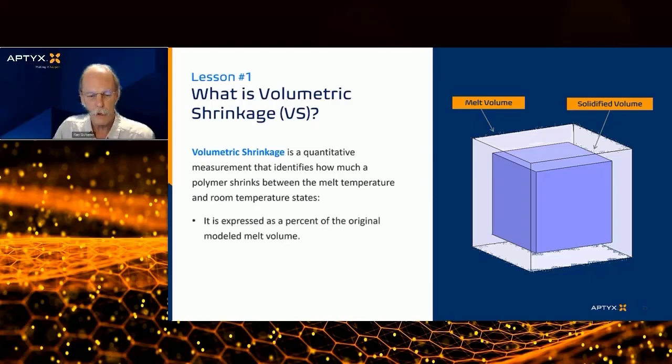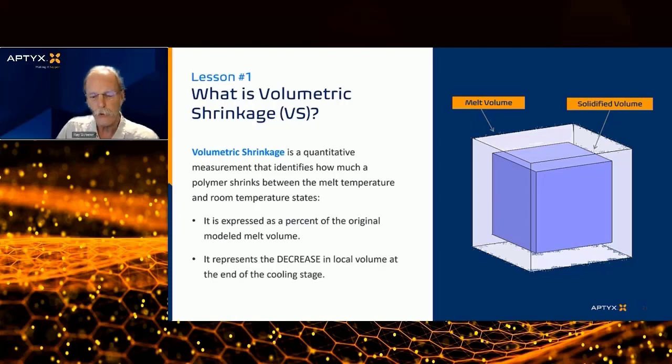So if you think about it a minute, what Moldflow shows is the percentage change. So basically, it's going to take that 100% volume, and it's going to give you a value and say, how much did we change percentage? Now, this is different than linear shrink. It's related, though. As we build molds, we use a linear shrink rate, and that just scales the part uniformly. But the reality of it is the part doesn't shrink uniformly. We'll get into that more.